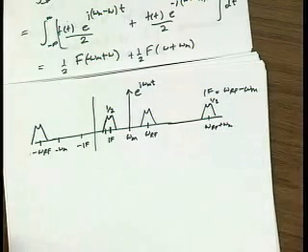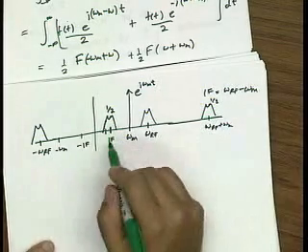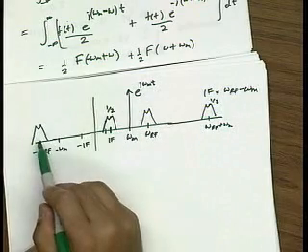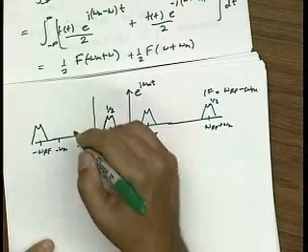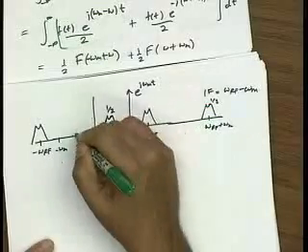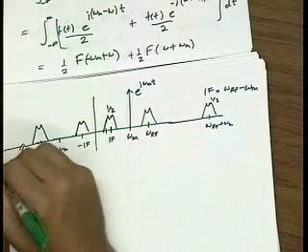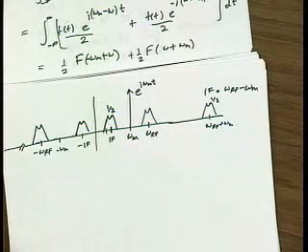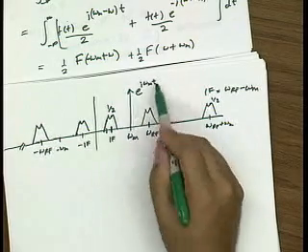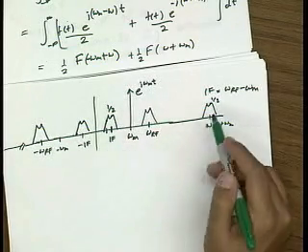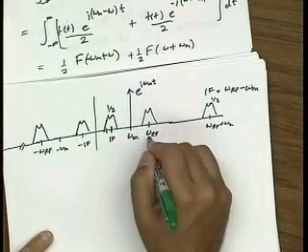Okay? And that's actually the desired down conversion, but because there's this negative frequency, I also have to take into account that I get a term which appears here and somewhere out here, which I won't draw. Okay? So just multiplying by one of these complex exponentials actually nicely does the trick. It moves my spectrum down to baseband.